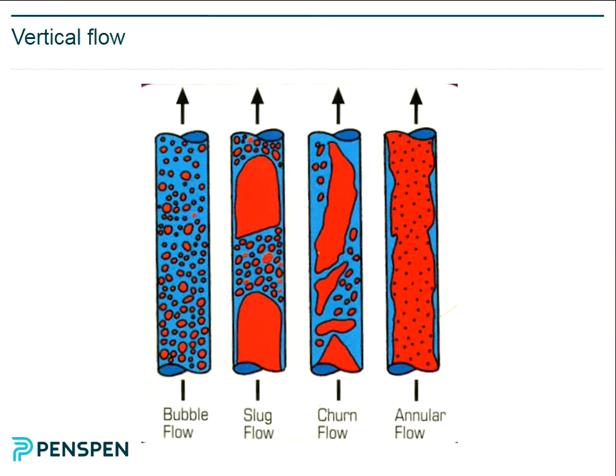perforations. So you introduce gas into the annulus, and then you have these side pocket valves which let gas go through at a certain pressure, basically, and that aerates. That produces multi-phase flow by the introduction of gas, which reduces the density, which increases the flow rate. So it allows the production of your well to increase.